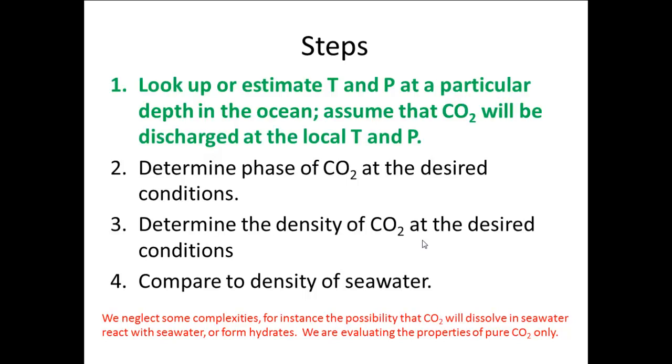Let's start with the first step. Since I'm interested in evaluating a thermodynamic property of a simple compressible substance, I need to start by knowing two independent properties. I'm going to look up or calculate values of temperature and pressure at a particular depth in the ocean, and I'm going to assume that the CO2 will be at the same temperature and pressure as the ambient seawater at that depth.